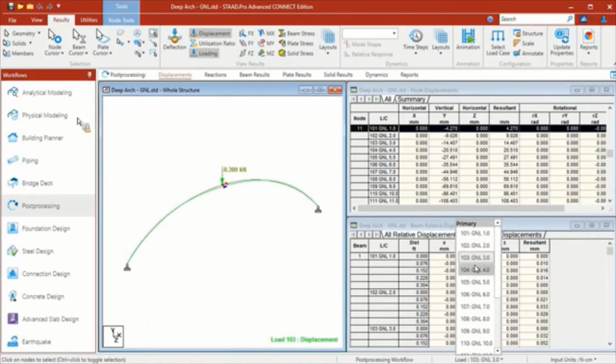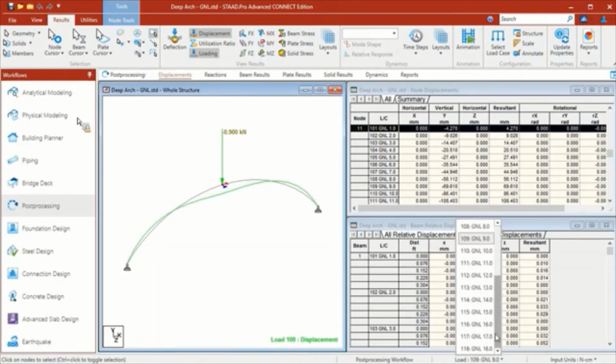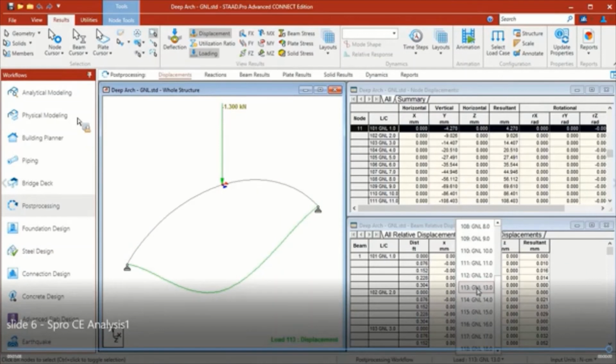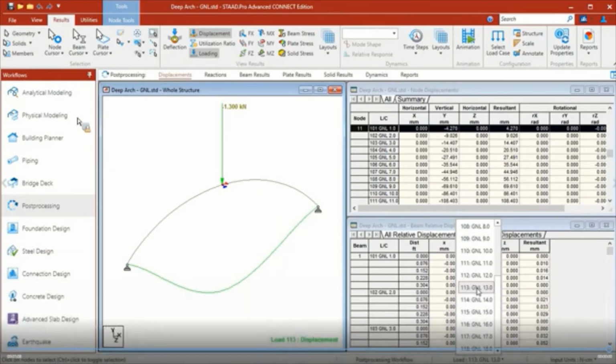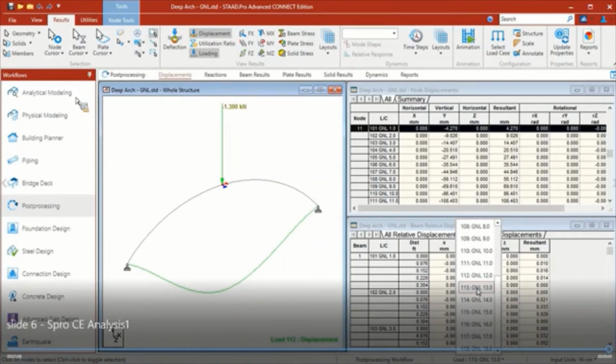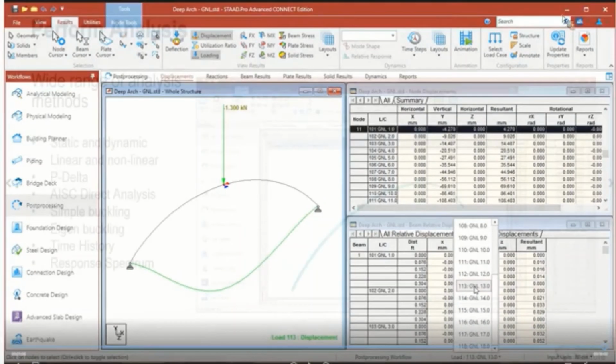You need to start looking at the effect of the geometric modifications that take place during the analysis, and have those remodify the stiffness matrix and get a more accurate simulation of the structural situation that occurs as a structure approaches a buckling criteria. So as we look at these situations, we want to be able to do that, and we can provide that with the STAAD.Pro Advanced solution.